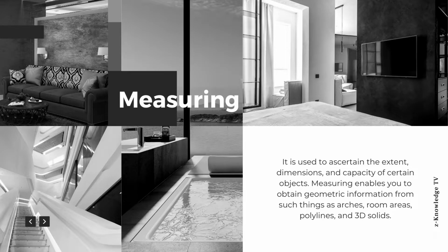Measuring enables you to obtain geometric information from such things as arcs, room areas, polylines, and 3D solids. So, we can calculate the distance, radius, angle, area, and volume of selected objects or a sequence of points by measuring. So, bali, mahalaga ang measuring when collecting data for building and manufacturing.